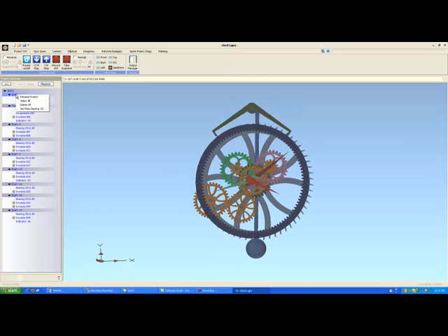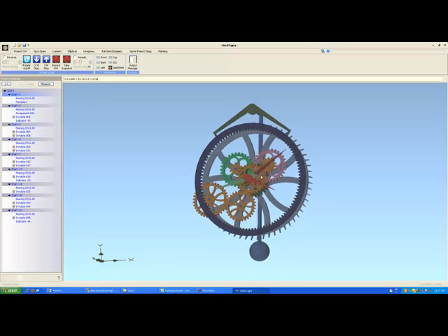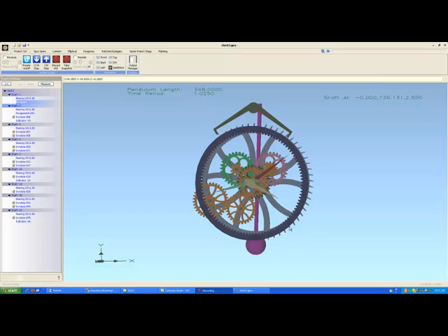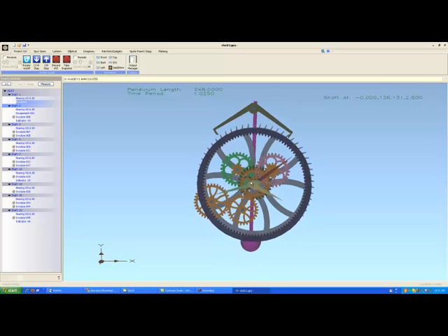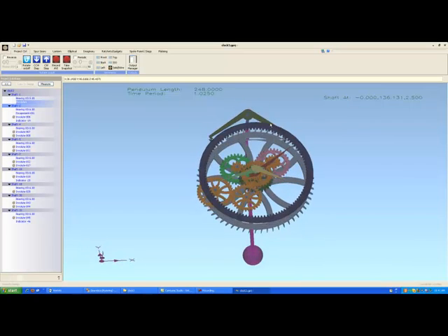Right-clicking on the shaft name will give you a selection for Set Plate Bearing OD. You can see if I bring it up, I can simply enter a new OD for that bearing. And this means, in this case, that I want to set the bearing to 10 millimeters for this particular shaft. The system didn't accept the shaft change because we don't yet have plates.